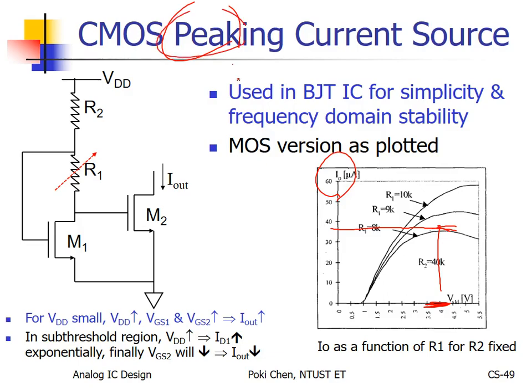Okay? I'm happy? In this way, we can make the output current quite independent of the supply voltage. But again, even though the output current is stabilized around your supply voltage, it is still very temperature sensitive.